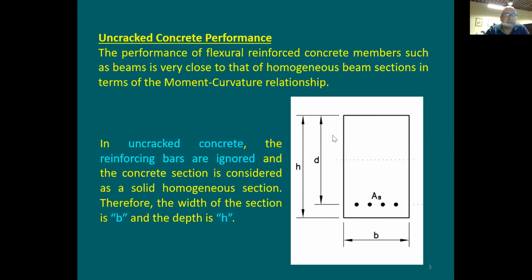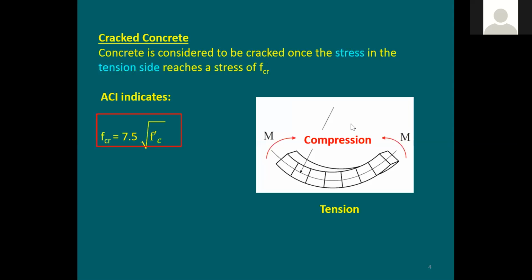It doesn't mean that the beam itself is going to get smaller physically, but with regard to analysis, the beam depth is going to be smaller than what you think. So let's say the crack depth here is going to be an inch. This means the effective depth that you can use in your analysis is going to be reduced by 1 inch. Why? Because the bottom inch of it is not working anymore.